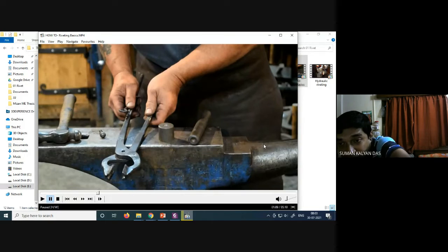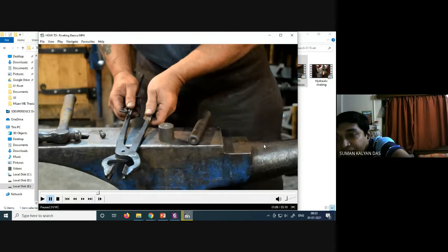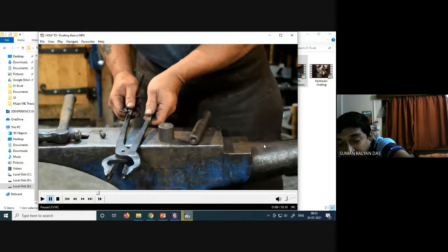First of all, your joint will be weak if you use a rivet material that has a lower tensile strength compared to the plates that you want to join. Obviously, the weak point is, first of all, due to the joining itself, the part is a weak link. Apart from that, the weak link is made further weak by selecting a rivet material of lesser strength.